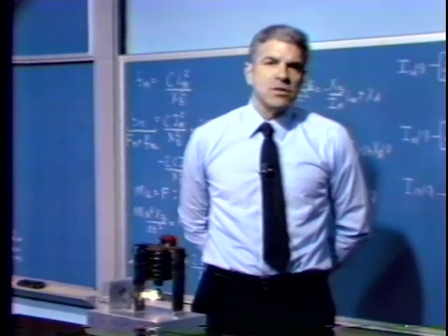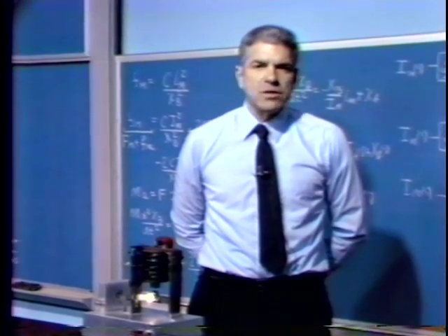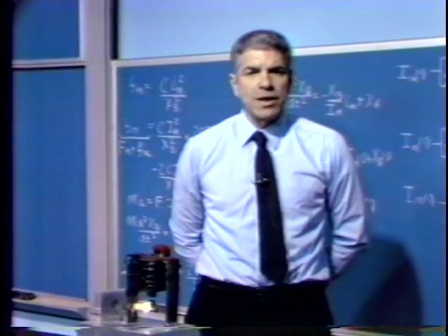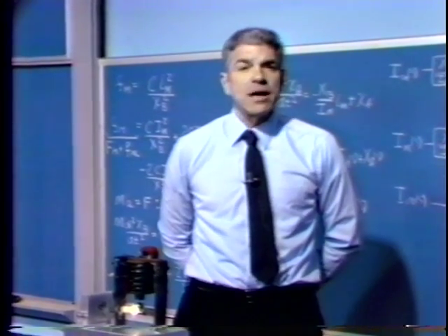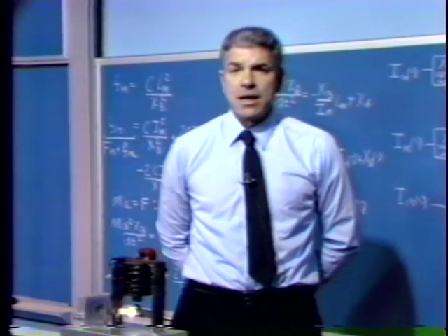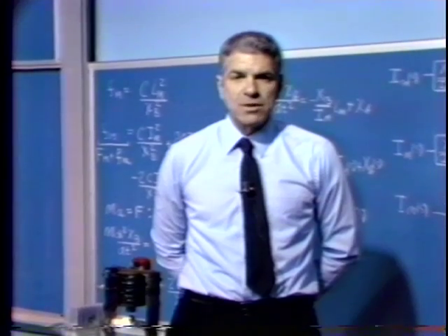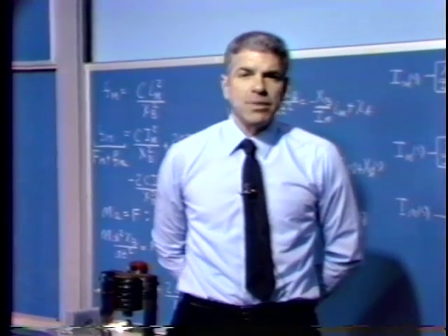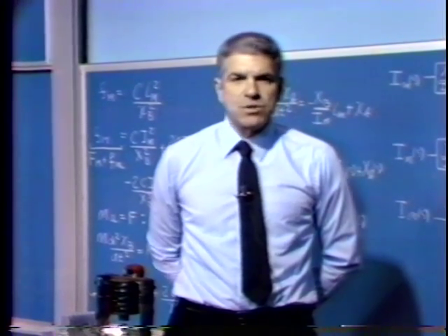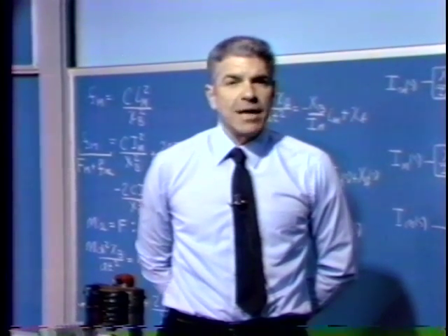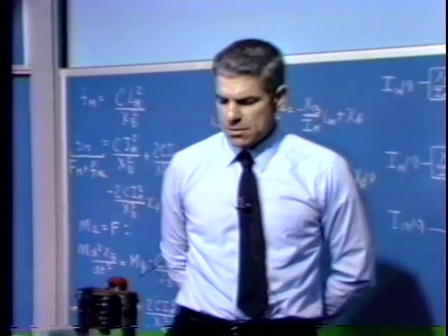We've then used our root locus approach to give us a quick look at what we might do to improve the situation, and we've decided on a compensation strategy based on that. In particular, what we'd like to do is add a zero to the loop transmission, and hopefully then by combining the zero with an appropriate amount of A naught, we're able to stabilize the system.